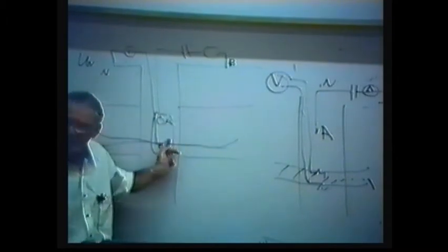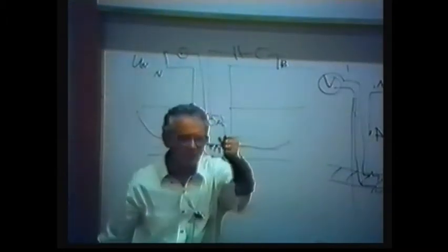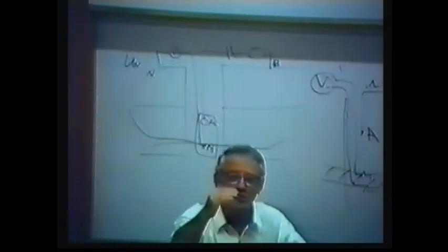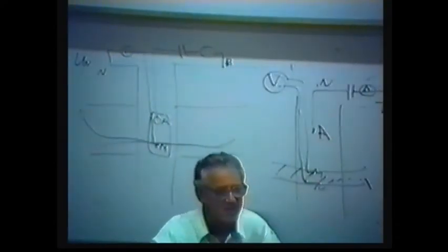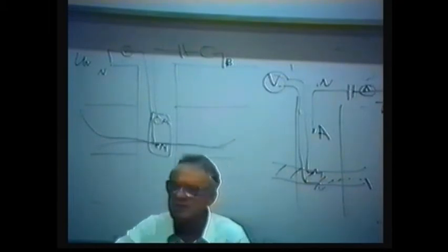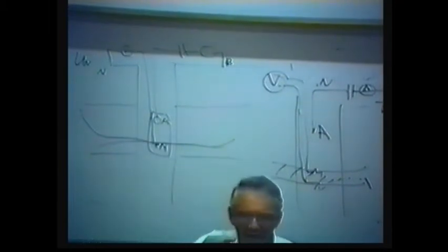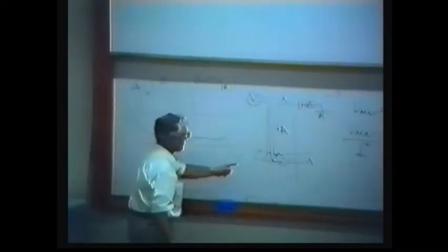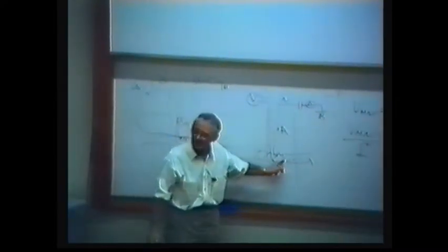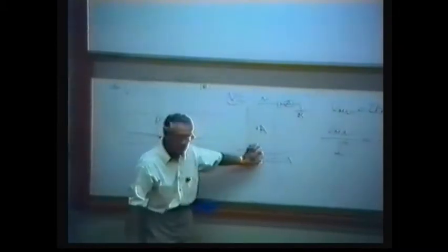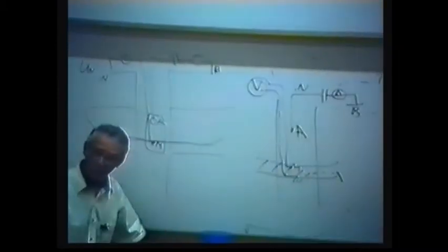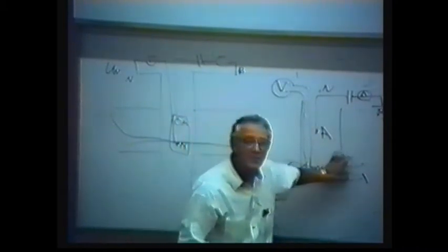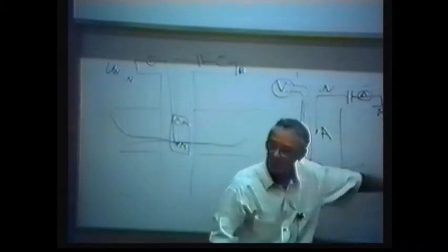It's very popular. When your device is moving along the borehole, it shows you change of resistivity. But we are interested not only to see resistivity, but we would like to detect boundaries. So this probe is more popular for this purpose. Why? Because it measures resistance not of the whole medium, but only the medium between these equipotential surfaces.